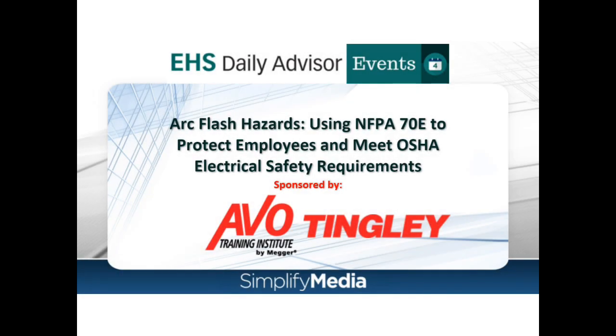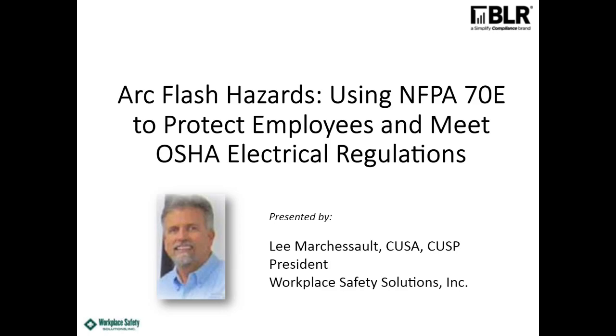So today we're going to be talking about electrical safety standards related to NFPA 70E and how that intermingles with the OSHA standards. Oddly enough, there's not a lot of OSHA information related to arc flash other than the utility standard that was updated in 2014. However, there is language in 1910.335 that requires employers to provide protection for the parts of the body that are affected by electrical hazards in the workplace.